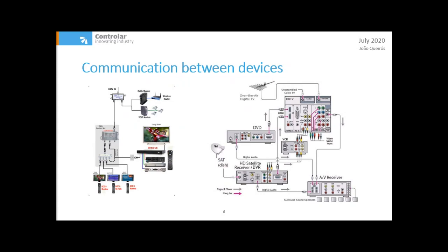Digital connections can be serial, where all the bits are sent one after the other on the same transmission path, or can be parallel, where several bits are transmitted at the same time in different lines, generally synchronized with the clock signal. The serial connections require fewer transmission lines to establish the connection, and generally have high clock frequencies to send data at higher speeds, where parallel requires more wires but less frequency to send the same amount of data.